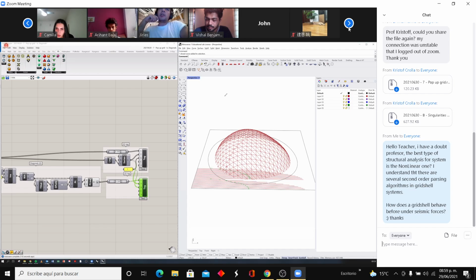Yeah. So normally, if you have one pole and then another one coming underneath it, oh, I'm drawing it very badly, you would kind of make your tie around it like that. Yeah, it's very coarse. And then indeed, if you then bring in your diagonal and you add another member running through it, then that one needs to be tied over the whole thing as well. But so in elevation, you would have something quite thick like that. You'd have your first knot and then your second knot over it. So that means you're starting to get quite a bit of movement potentially there. It becomes quite loose. But that's fine. That works.